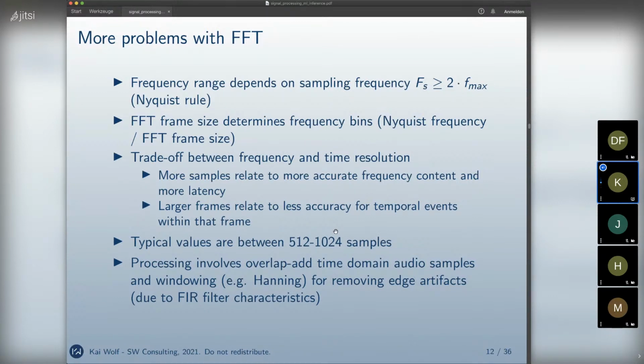This depends on the signal we are trying to analyze. So it's good to have some understanding of your target signal beforehand. Say if we want to analyze a bongo drum, which has snappy short sounds, I would just look at a small FFT frame, because the frequency bins are linearly sized in my FFT frame, so it would look much better in the spectrum than for a large FFT frame.